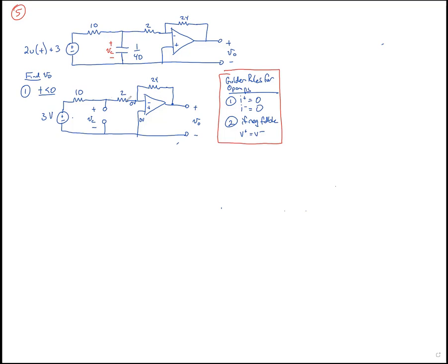So let's do a KCL someplace over here. We could do a KCL here, not super interesting since we know it's 0 volts. Or we could do a KCL here, which is very interesting because if we call this ground, which is a reasonable place, then we've already named this node VC. So let's try doing a KCL up here.